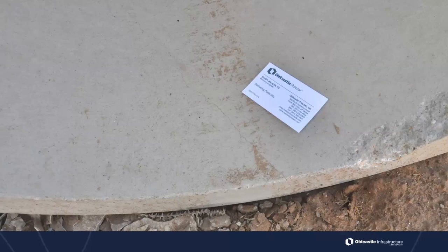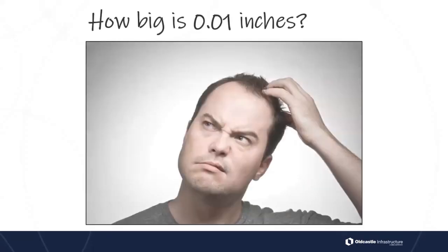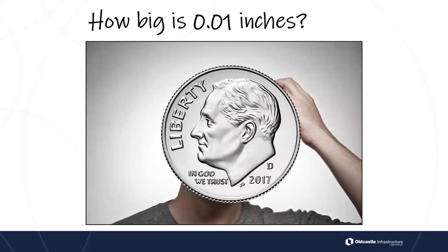But what I wanted to point out was how small that crack is, and sometimes in a video it can look really big. So we don't want to do more work or more damage to the pipe system by removing a pipe that actually meets the acceptable standards. So you might be asking yourself, how big is 1/100th of an inch? I want you to imagine a dime. Okay, take a dime, pretty thin, that dime there.